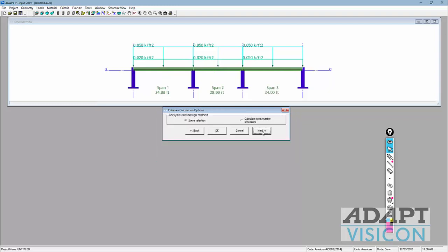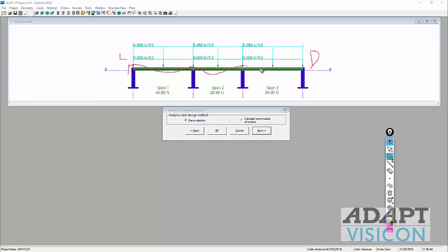So the design method can be either effective force, where let's assume that this is our live end, this is our dead end for our cable, and we might have 3 reverse parabolas in here. If we were to graph the losses here, we might have a loss diagram that looks like this. If we actually calculate the losses, plus we have some seating loss, this would be based on, let's say, the actual condition. So the actual condition here looks like this.